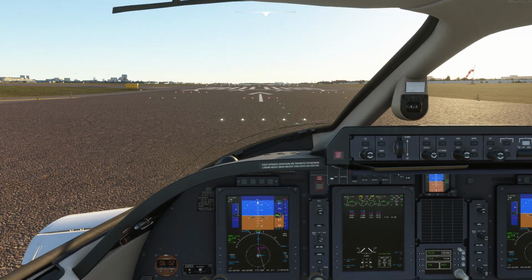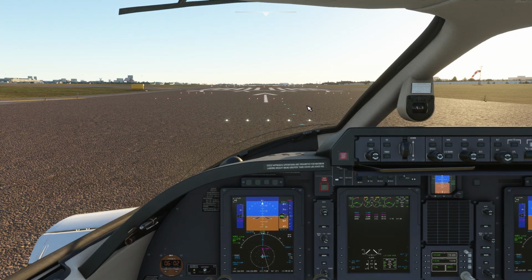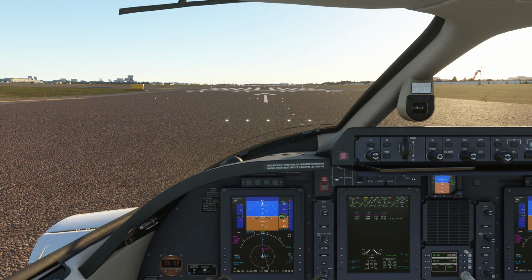So after takeoff, we'll retract our gear, we'll climb to a speed of around 120, and then we'll retract the flaps, and our aim will be to climb at the speed of 160. Right. Navigation source to FMS. We'll disarm the brake. I'm just holding it manually.